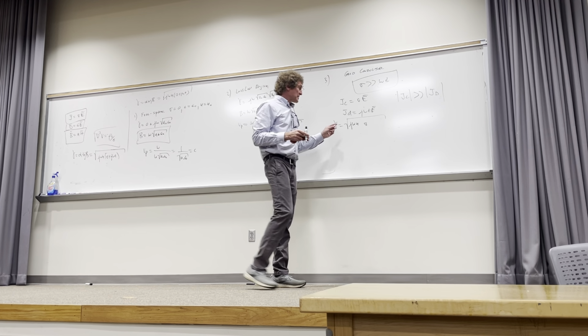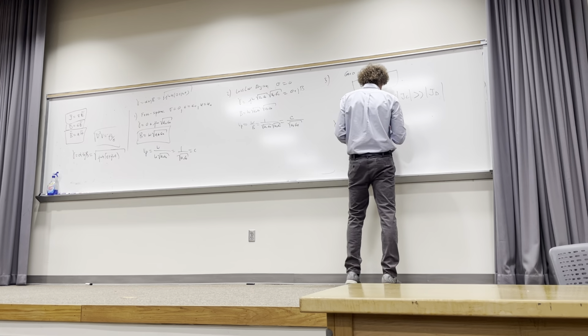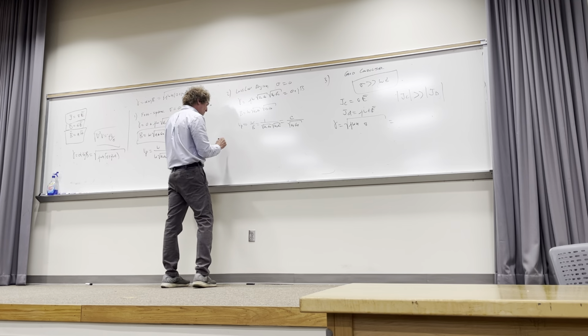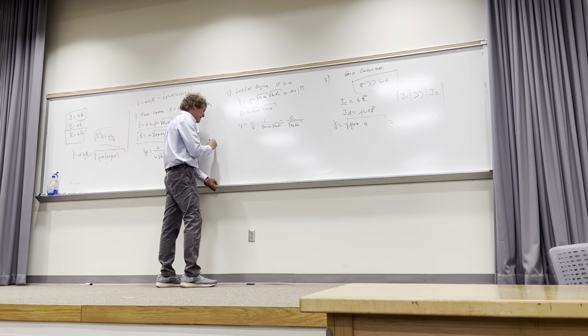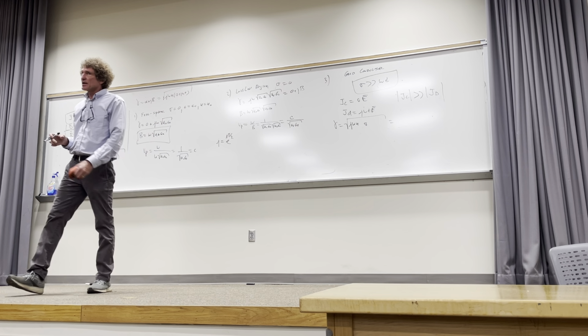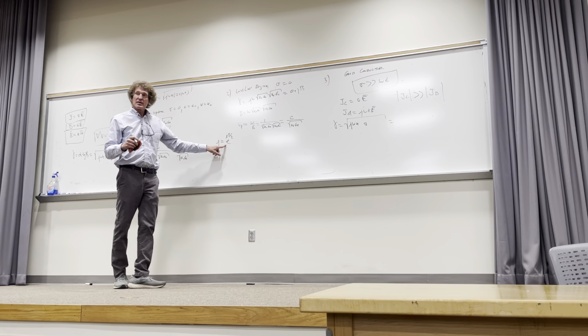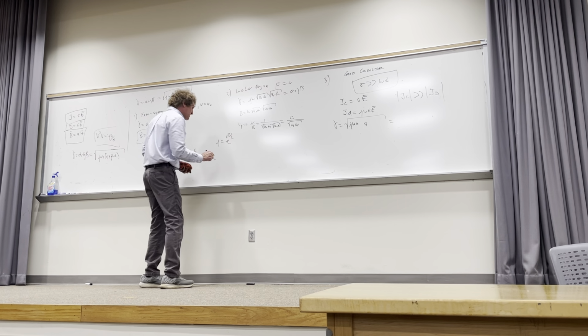All right, now what happens there? If you wanted to write j a couple of different ways, j is actually equal to e to the j pi over 2. Isn't that right? Just think about that. j is the square root of negative 1, that's one take on it. It's really 1 at an angle of 90 degrees, right? So in the phasor domain, this is 1 at an angle of 90 degrees, right? What's the square root of j?